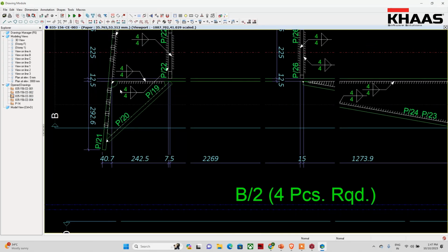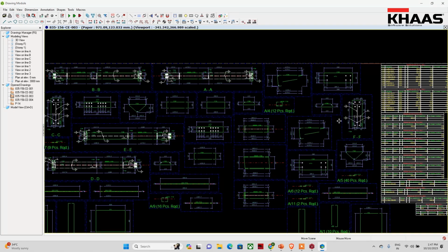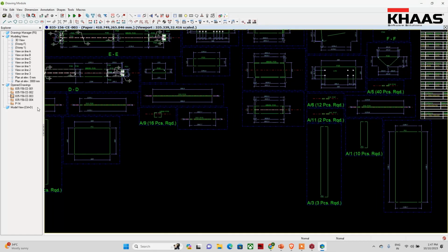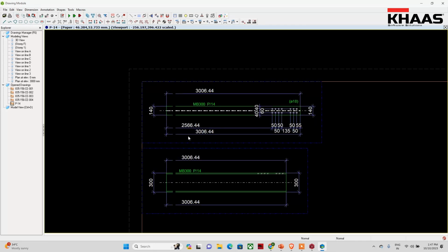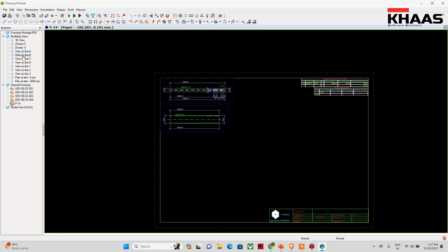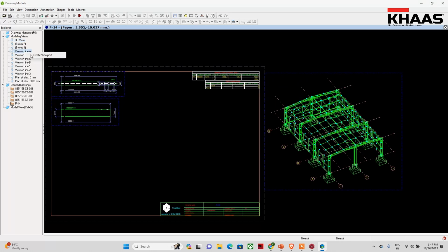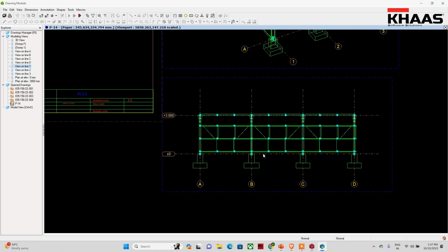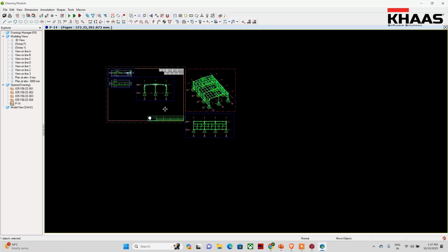So the same for other details like the part of B cross 2, the beam, B cross 1, the part, and you have some quantity takeoff, and we can add the details here. So this is a part list of some of the details. If you want to take a separate part alone, you can also take that. So let's say, for example, right over here I wanted to add some details. You can do it, for example, a 3D view. I got it there, and if you want to take the V1A, you want to take a V1 line 1, just right click, you can generate the details, and you can make a scale and arrangement, and you can fix it. As simple as that.